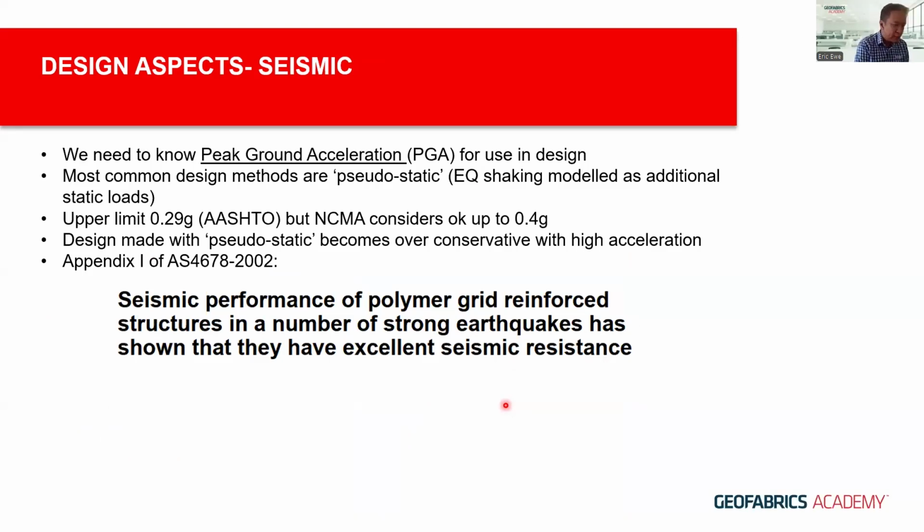Seismic is obviously a very important consideration for the design of this type of structure, especially so in New Zealand, not so much so in Australia. For that, we need to know the peak ground acceleration, PGA, in the respective zone where the structure is located. Most of the common design methods use pseudostatic, i.e. the earthquake shaking is modeled as an additional static loading.